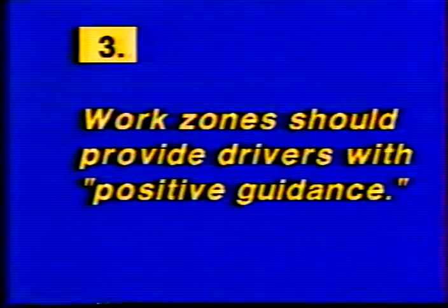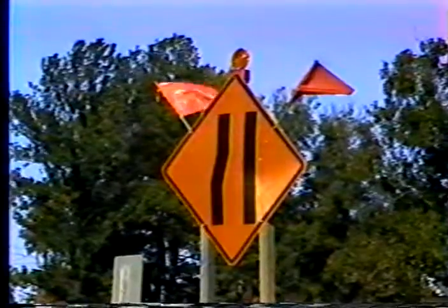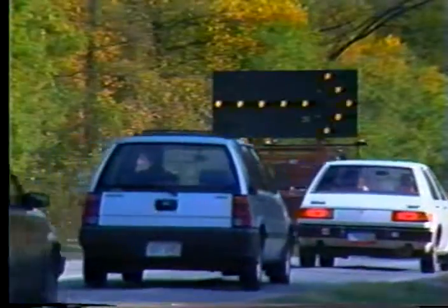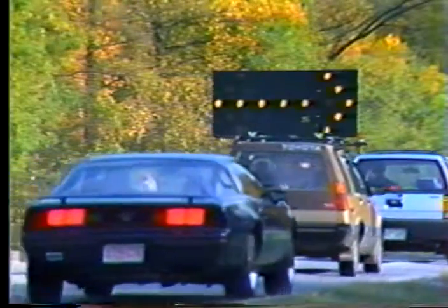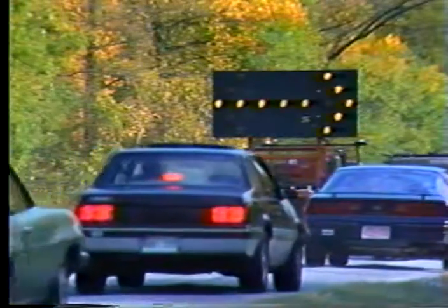The third basic principle of work zone traffic control is that it should provide drivers with positive guidance. Positive guidance means telling drivers what to expect up ahead and then showing them the way. Good traffic control eliminates choices. There should be no question about the path to follow.